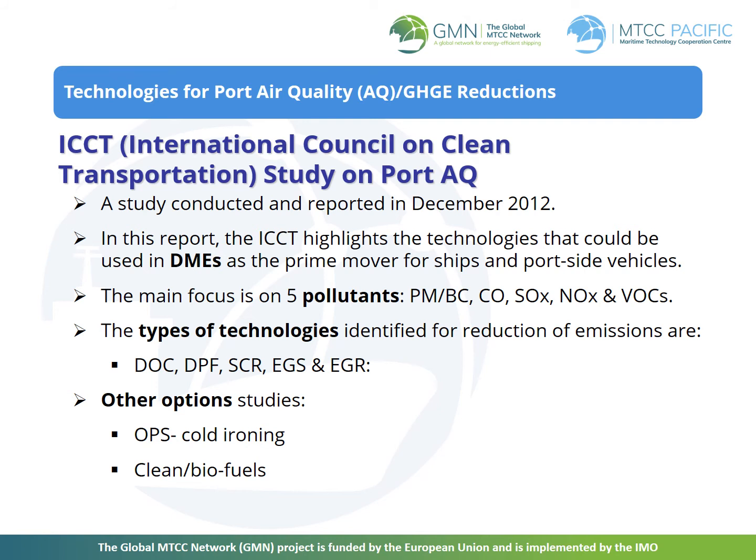The type of technology identified for reduction of emissions are diesel oxidation catalysts. This is a device installed at the back of the engine on the exhaust gases passed to oxidize such pollutants as CO, PM, and HC.